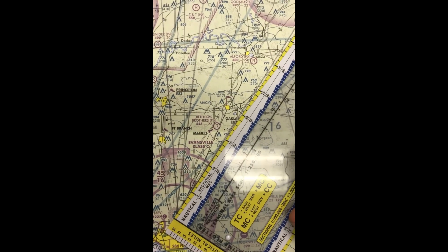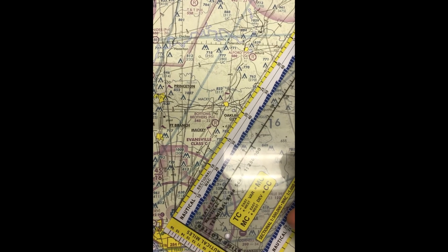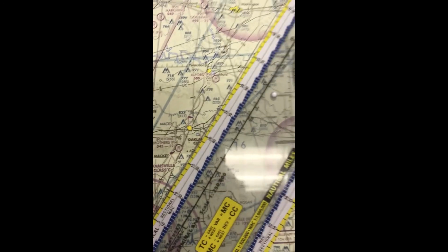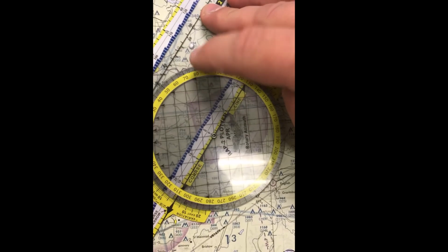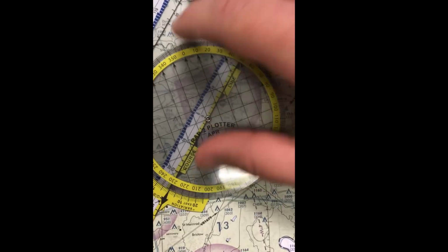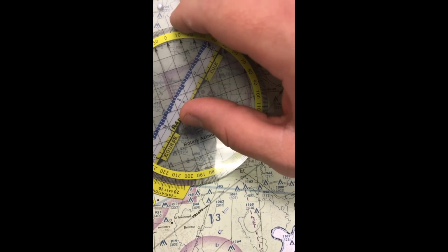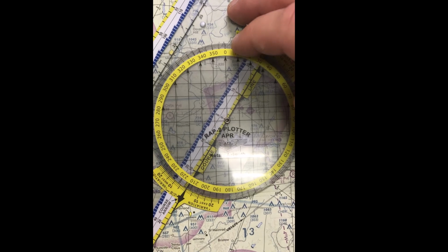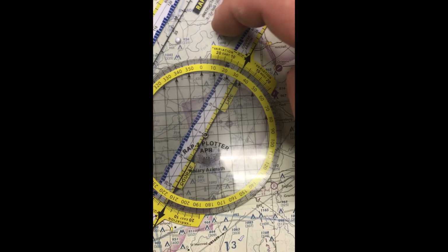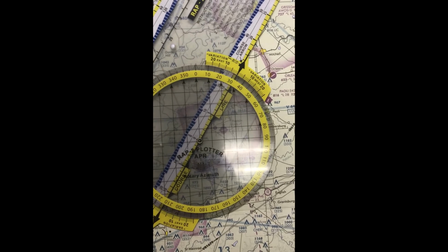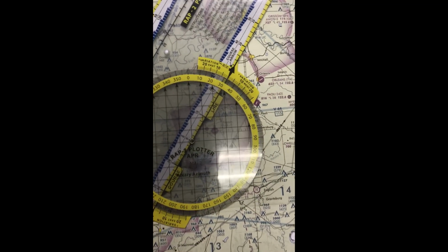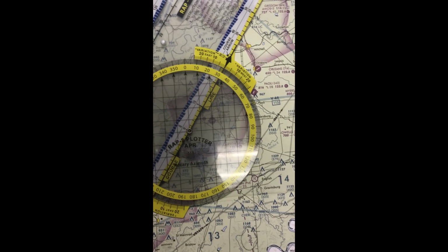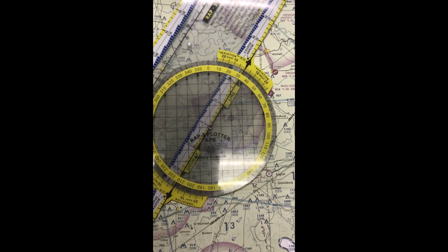All right, so instead of having leg one, this will be our climb portion. We'll call it 10 nautical miles, and over here we're going to have to come up with a course for that. So just like we did on the last one, we want to go ahead and align our straight edge with that course line, get those lines roughly parallel to one of those lines of latitude or longitude. And under the course line, we can see our initial true course for our climb. We'll go ahead and call it about 033 true. So we'll jot that down, and we'll keep that for later when we start doing all those individual calculations.